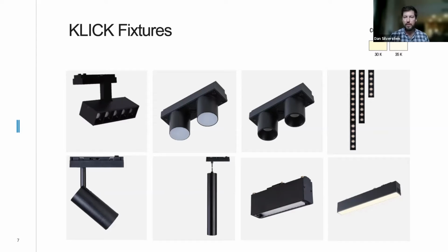The next one moving to the right is what we call the multi-spot. It's available in 5, 10, and 15 LED modules, and those are 200 lumens per LED. So your 5 light module is 1,000 lumens, then 1,500 lumens, and then 2,000 lumens as you move up through the different sizes. And those are, again, 10-degree spot LED reflectors, so a really tight punch of lighting.